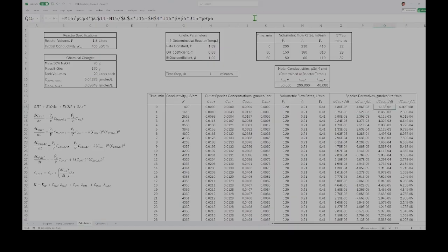And we would end up with a similar equation for the ethyl acetate, but in this case, what's coming in is the volumetric flow rate of stream 2. And for our acetate ion, it's going to be equal to what's leaving in stream 3, which will be negative because it's an outflow, times its ionic concentration, plus what's generated by reaction, which is our rate constant, our hydroxide ion raised to the alpha power, and the ethyl acetate raised to the beta power.